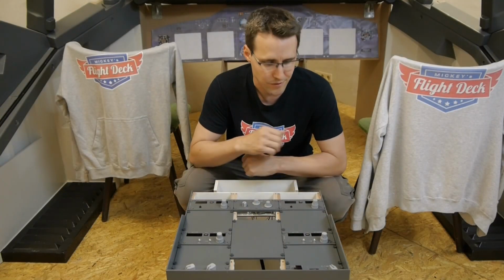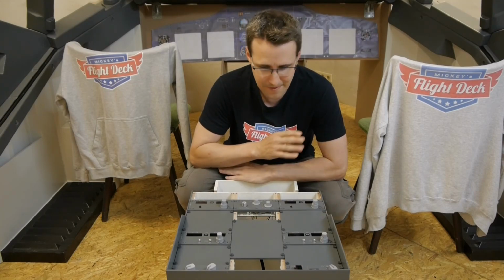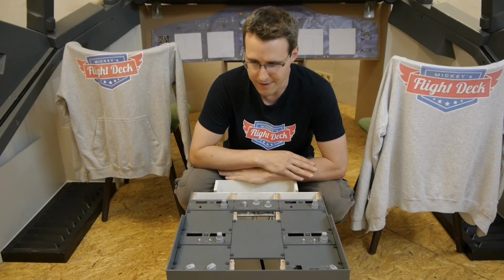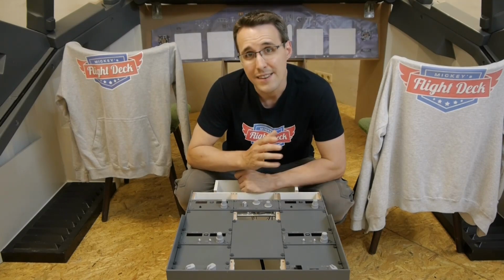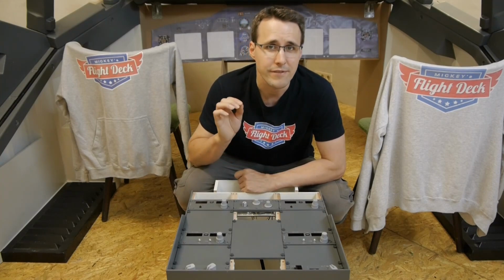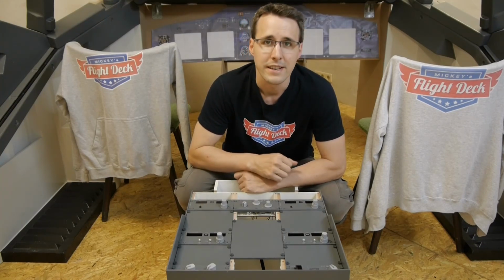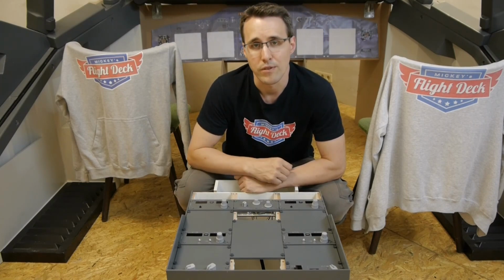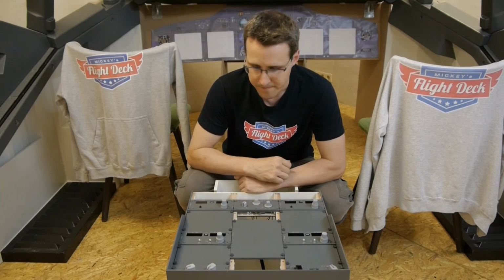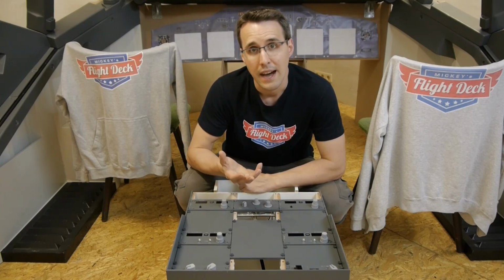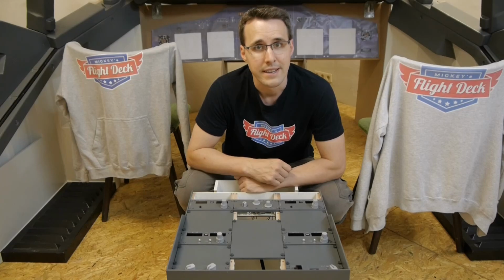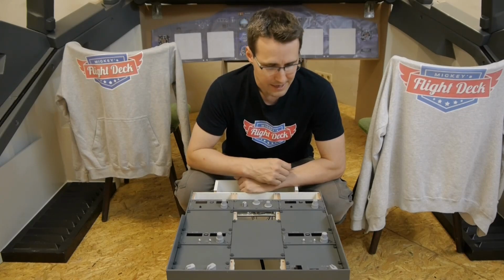And here are the 2 panels in place. Nice to see that more and more panels are finding their way here now into the pedestal. And it was a good example that even if you look up all the documentation, you still can be faced with problems you have to find a solution for. In this case, I have shown you a way how you can connect these panels to the simulator via Prosim and MobiFlight, so you can save a lot of time.